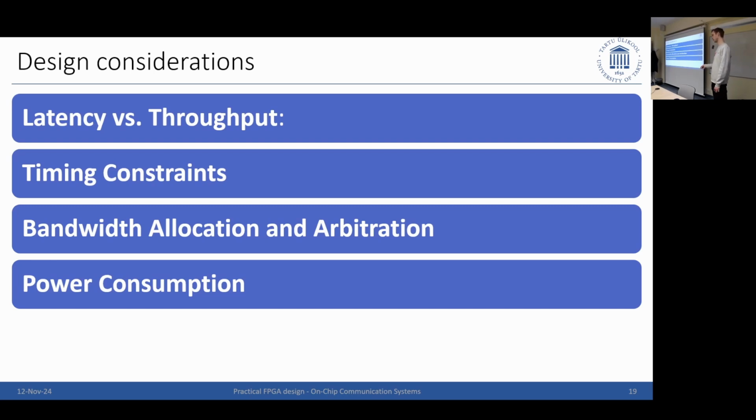What I've learned in FPGA is to have a draft early on of what interfaces I have, what speed I need, and how much data throughput I have between the different blocks. Figuring this out earlier rather than later will help you decide early on how efficient the design is, and you do not have to change it. And as said in the last lectures, it allows you to do test benches, analysis of the design, choose which device you want, and those kinds of things.